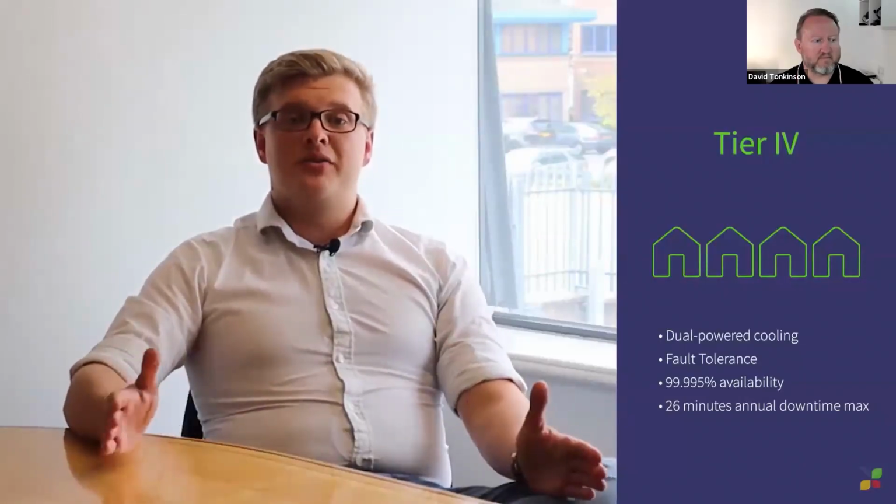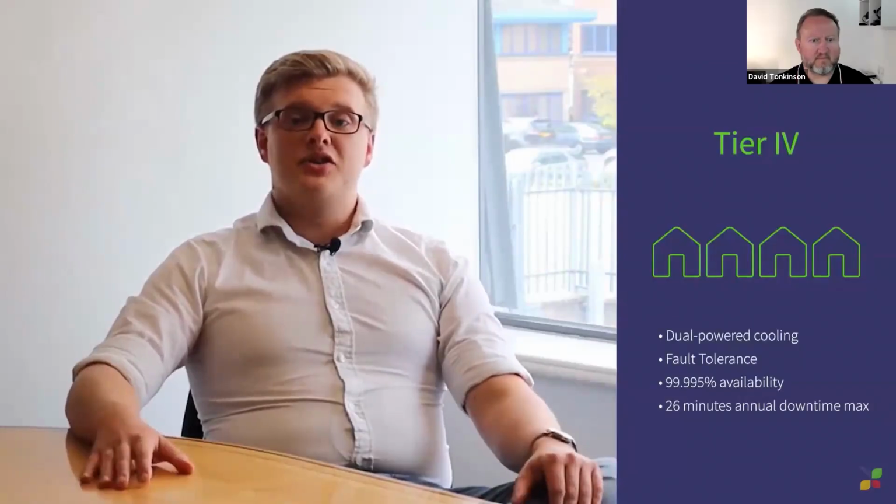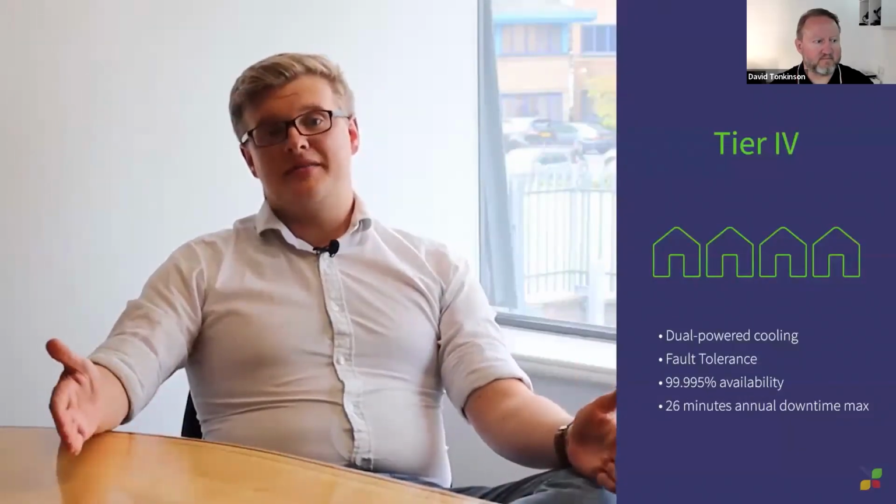Each of those power paths will have its own resilience in. So you can think of it like having 2 tier 3 data centers effectively, because you'll have tier 3 standard on each of those paths. There's very few tier 4 standard data centers, just because the cost of adding in that additional level of resilience generally outweighs the benefits of doing things like good proactive maintenance and good testing of the systems.